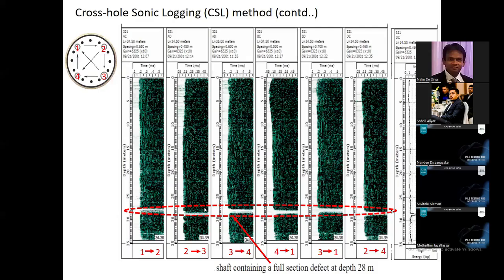So once you detect this kind of defect along the pile, it is a must that you drill some cores, right? Concrete cores, and rectify the pile by grouting. So this is where you need to do coring, right? Once you encounter this kind of area-wide defect.